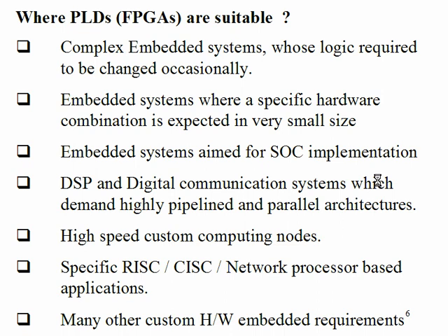ASIC. I'm just waiting for that word, ASIC. So when you design, let's say, an embedded system in a single chip directly, at the layout level you designed, you send it to the fab, got the chip manufactured, you are happy, you are running with the chip, but somebody told you change the design. Come on, once you change the design, everything should be redone, and a lot of money is involved in doing it. So generally when you make an embedded system at the silicon level, meaning ASIC level, they are not reconfigurable. But all other types of embedded system, microcontroller, microprocessor, FPGA, they are all reconfigurable.